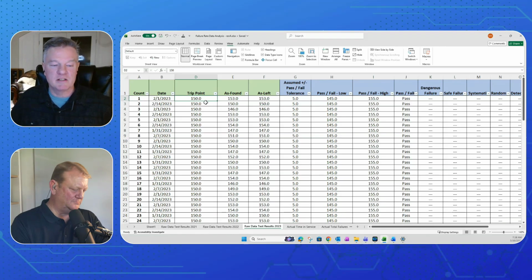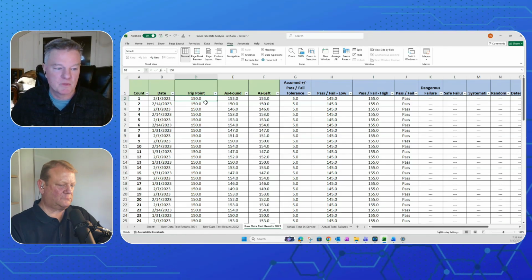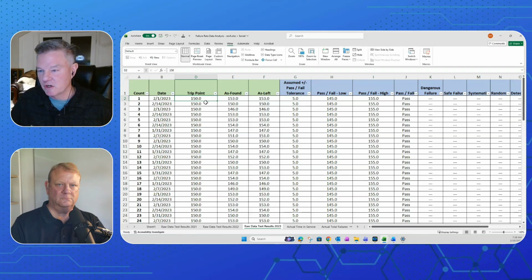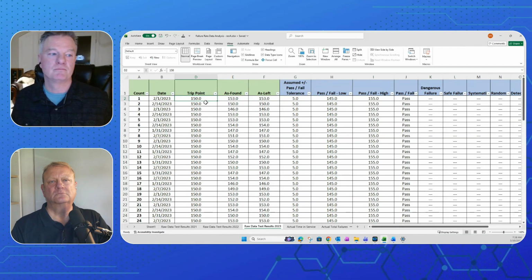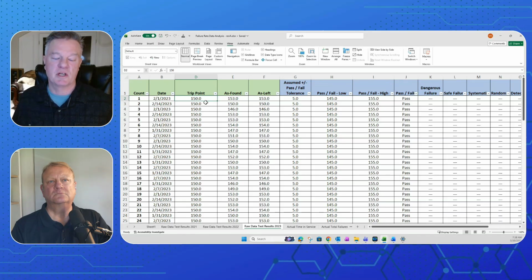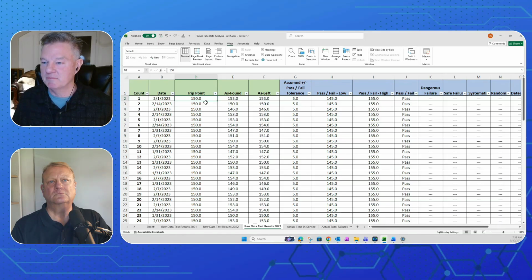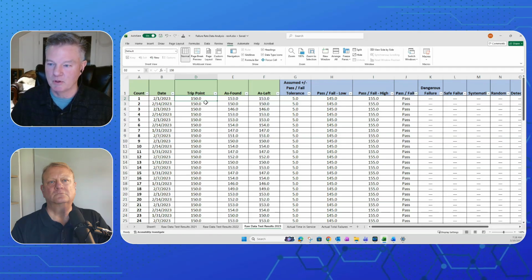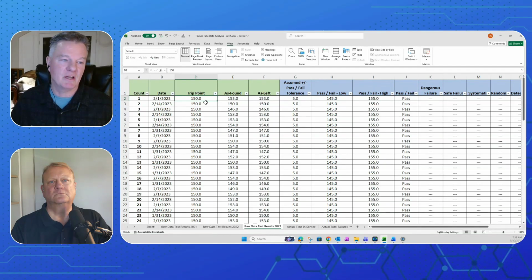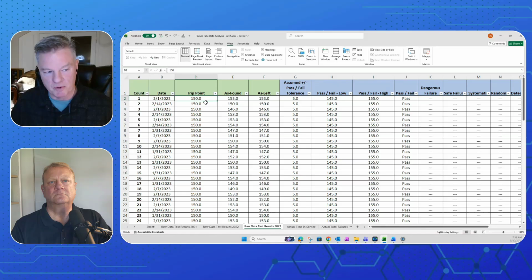Okay. What we're looking at is positive displacement pumps. There is no relief valve at the discharge of this PD pump because they're making product. Let's pretend it's paint. If it's red paint, in that dead space under the relief valve, red collects. The next time they want to make blue, the red bleeds in. The next time they want to make brown, the blue bleeds in. So they can't have the relief valves in there because it screws up product quality.